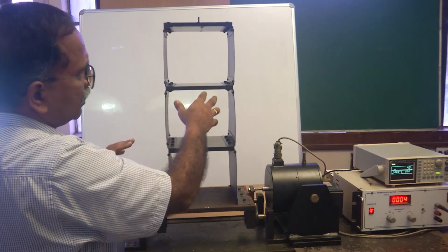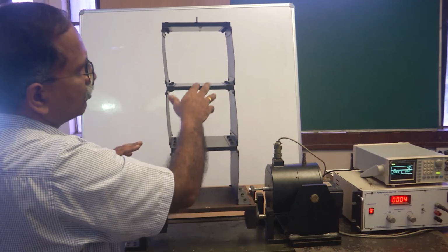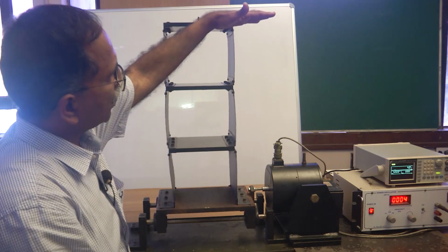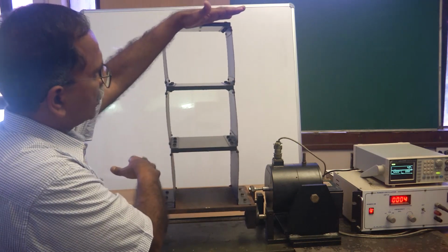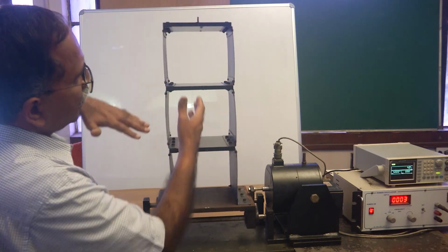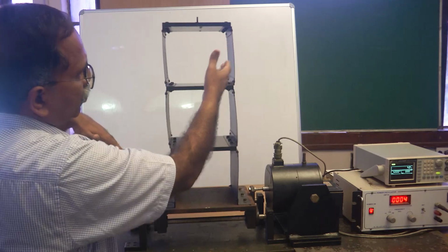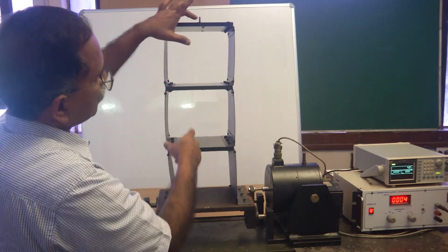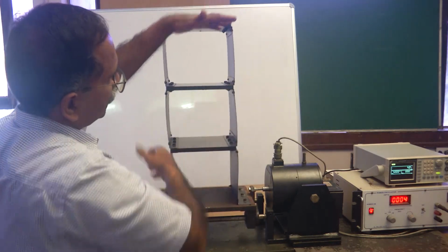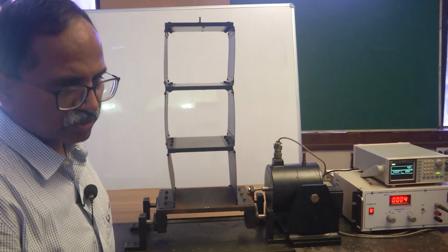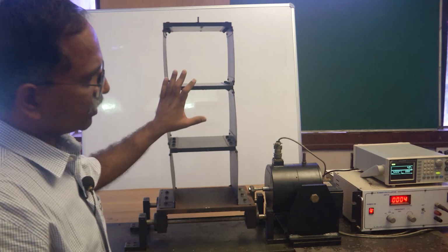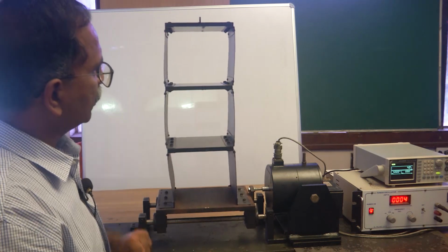This plate is not exactly 0, it has some motion, but that motion is very small compared to these two motions, and so you have +1 here and maybe some amplitude here that you can find out through numerical calculation. But you expect to get a 0 displacement location between this and this, because this is moving this way and this is moving this way. So, if you join all of these, there will be some position where the displacement is going to be 0. So, that is how the second mode appears here. This is a resonance corresponding to the second natural frequency.